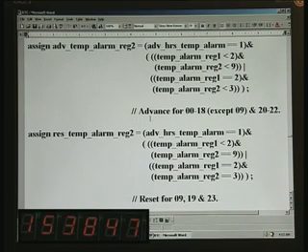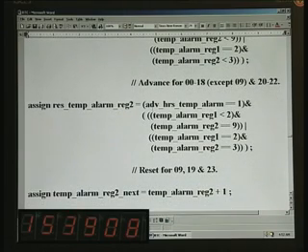I am going to read only the comment. So here you are going to advance this alarm setting only if it is 00 to 18 other than 09, and 20 to 28, only then you need to advance, right, not otherwise. Similarly, you can reset only when it is 09 or 19 or 23. This is as far as the second register is concerned, which corresponds to 9 or 9 or 3, because this is the terminal count.